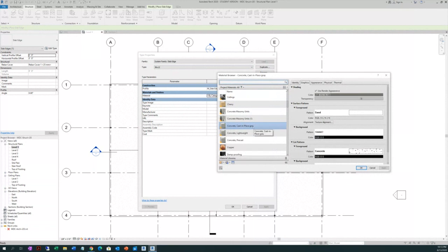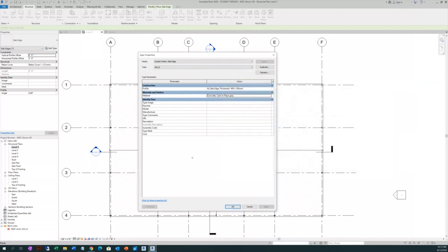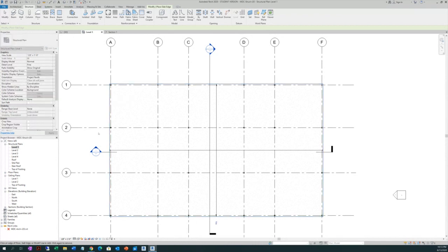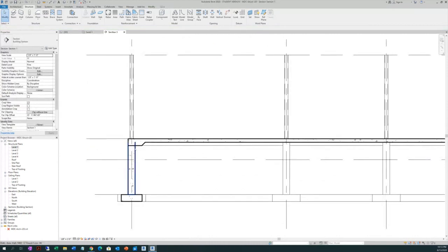Select the material. Okay. Then I can come and hover on the edge of that slab that I have here, hover and press Control down on my keyboard. That is a change selection, and I click. I may have that slab edge down. That's what I want.